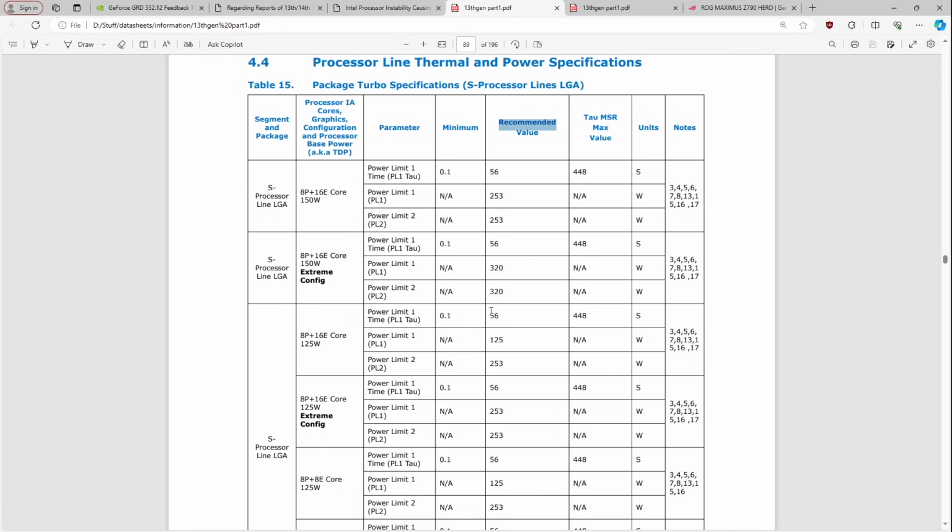So if you're hitting the thermal limit, you're not necessarily at peak current draw, right? These chips will pull some absolutely insane amounts of current. So if the CPU is thermal throttling at 100 degrees and 1.3 volts, that's actually less current going into the CPU than 100 degrees at 1.2 volts, which is kind of a weird thing, where you potentially would want the CPU to be thermal throttling at a higher voltage rather than a lower voltage, because at the lower voltage, it's going to be pulling more current.